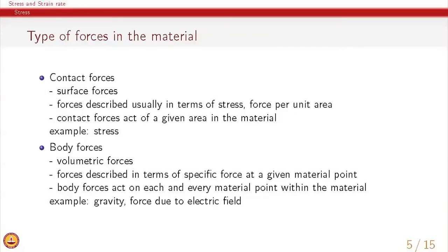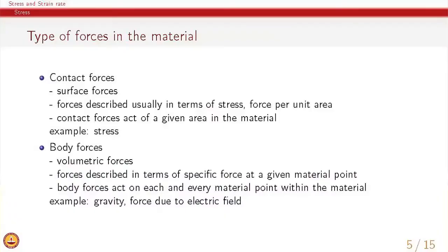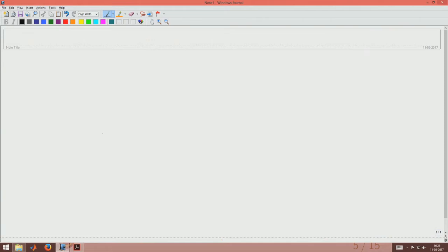So, let us look at how to define stress, and what are the different types of forces which we can most generally define. Basically, what we have are contact forces in the material and body forces. The contact forces are essentially forces which act on surfaces, which is why we can refer to them as surface forces. They are forces described only when we define a surface within a material. So, let us look at what we mean by this.